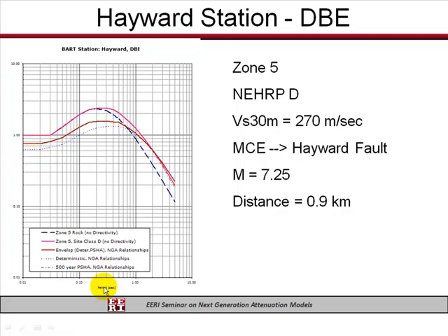So you can see right off the bat for this station, if you were designing something to a PGA at the DBE level, you can get about a 25% reduction in ground motions from using the procedure that was used in 2002 and updating those with the NGA. That reduction in ground motion is fairly consistent until you start to get out to the longer periods. And then actually for this case, as you get out to very long periods, there's pretty much an equal design level that you would achieve using these updated motions.